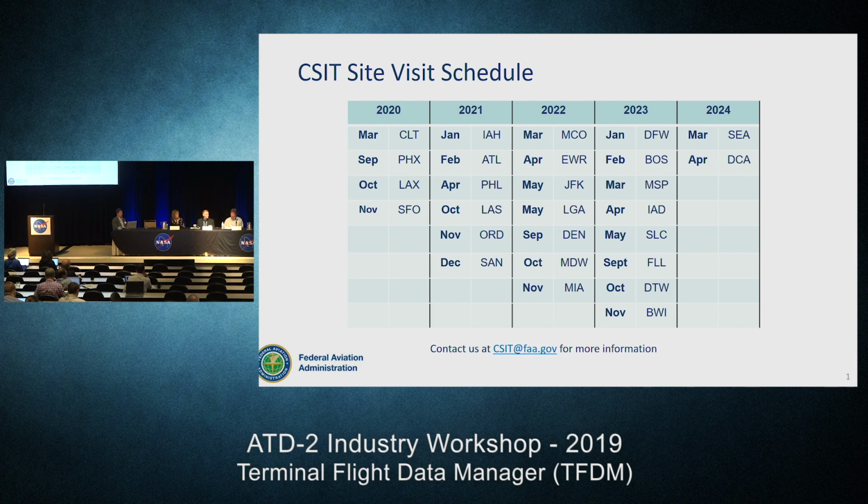Some of the valuable lessons learned from ATD-2 that have been helpful for us, and I'll just bullet point them very quickly, is that surface metering works. And you get benefits. If you hold an aircraft at a gate for 5 minutes, you get that 5-minute benefit. But you also get a benefit of an improved taxi situation on the surface, on the ramp, where you don't taxi out as long. So there's another few minutes that are gained on the taxi to the runway that I would not normally have anticipated.